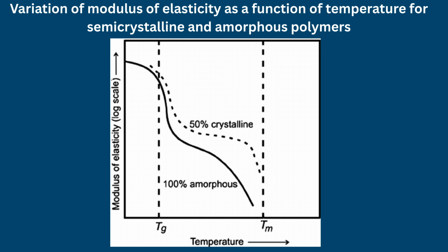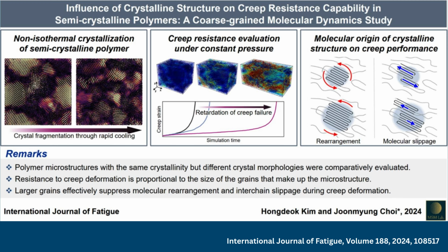Time-dependent behavior. Because the amorphous phase remains mobile above Tg, semicrystalline polymers exhibit significant creep and stress relaxation. Under constant stress, molecular rearrangement produces time-dependent strain, while under constant strain, stress gradually decreases.